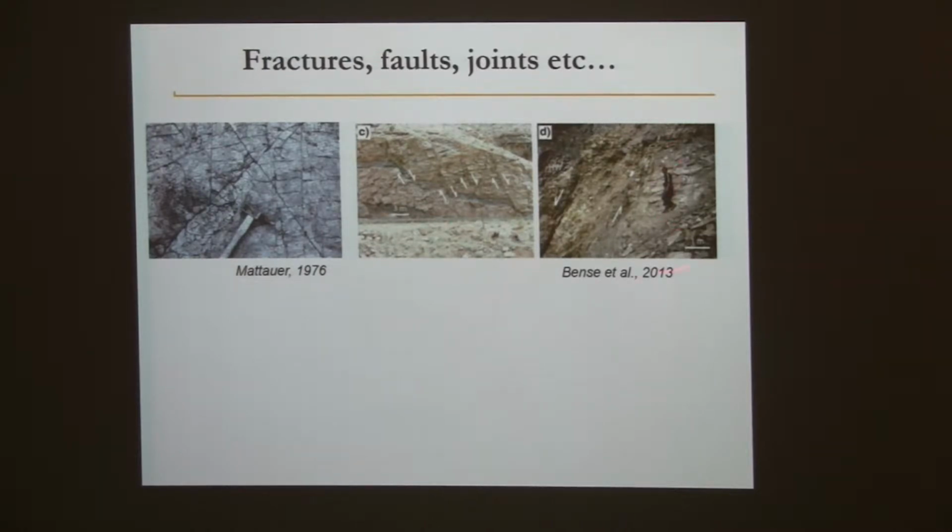And here what you can see is an even larger fault. The scale is given here, and what you see is that this is what we call the hanging wall and the foot wall. The two parts of the rock slide on each other, but between them, in the fault zone, you can see this material. This material is not the original rock, it has been transformed. It's typically what is called a gouge, and it may strongly modify the permeability of the medium.